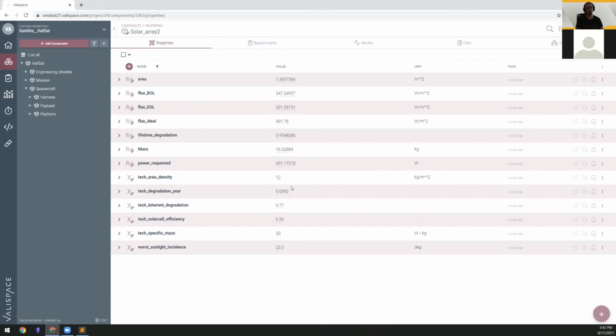And you can also reference values between projects. So maybe one idea would be to have one project that defines your satellite, the satellite for your constellation, while another project is for the constellation itself. So you can get all the properties of the satellite, but keep the constellation as one isolated system in a different project. If that makes sense for you, because it might have some extra overhead, but you will have that a bit more separated if this is necessary. So it depends. It will be case by case which one is the better alternative.